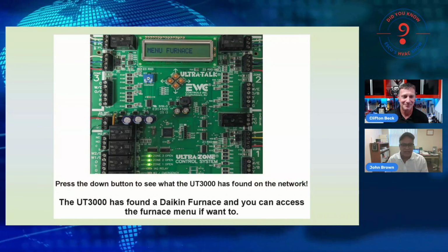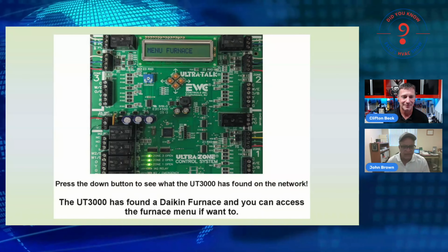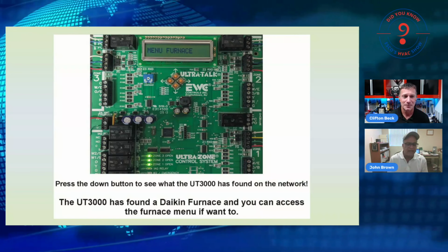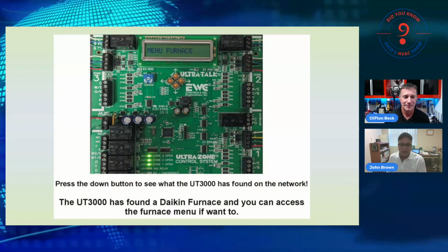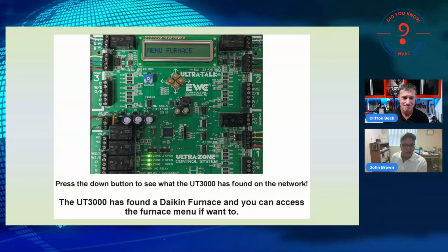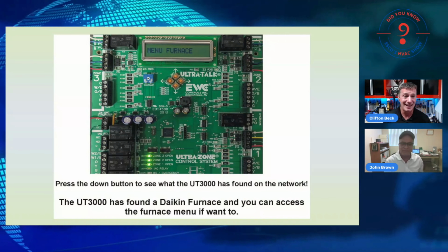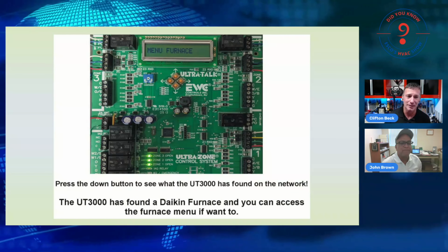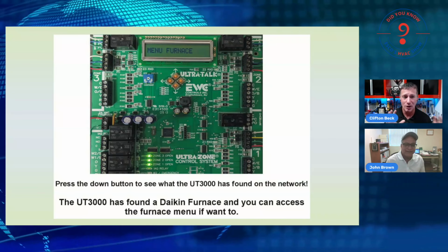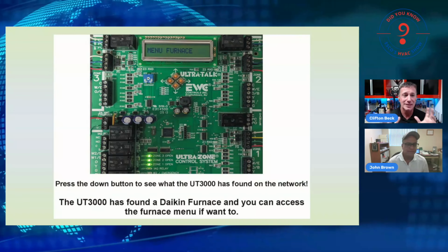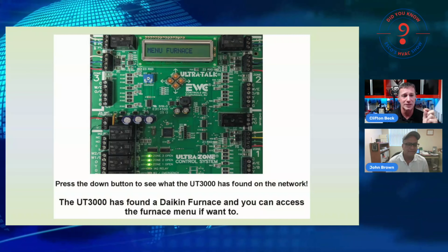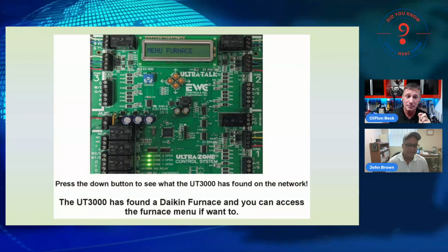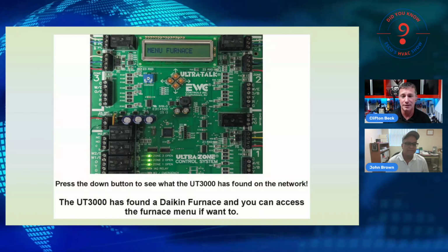I can access the diagnostic folders if I wanted to, clear diagnostic faults, all kinds of things. Anything you can do in the equipment menus with a thermostat, you can use the zone controller to do. I love it. You're inside, you're high and dry. You can put it in system verification test and start taping up seams, sealing ductwork, picking up your tools, not running back and forth, because we have eliminated the perception of requiring the thermostat to do the commands for the system. It's just a component. It receives and it transmits just like everything else.